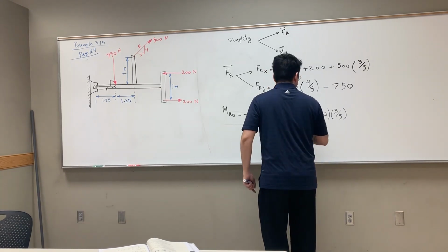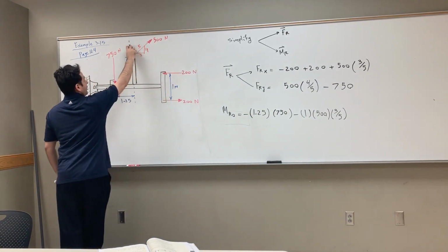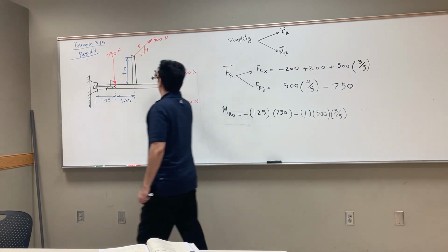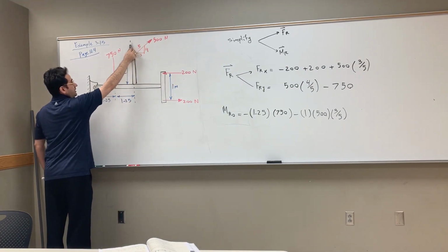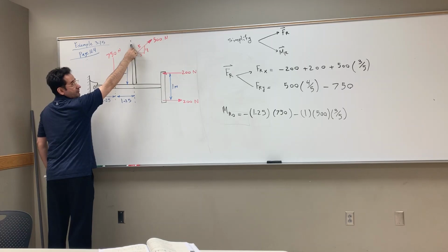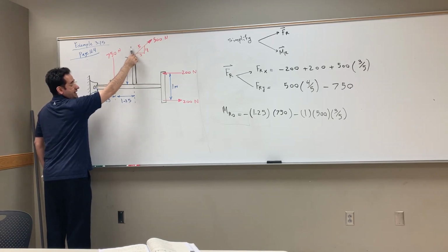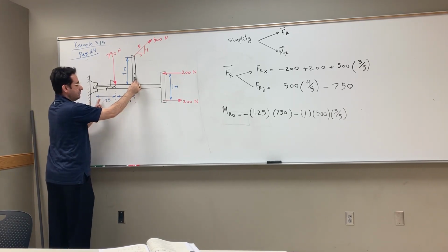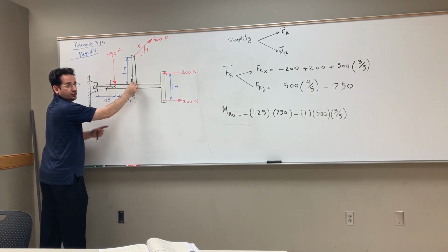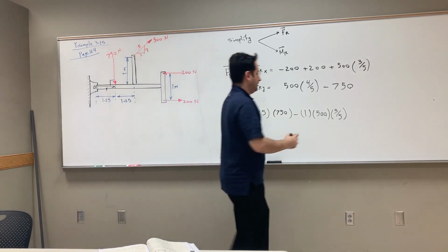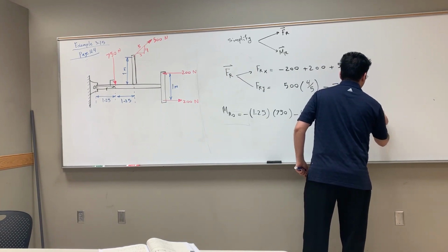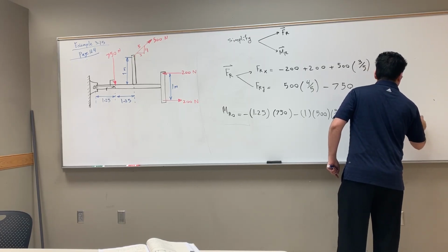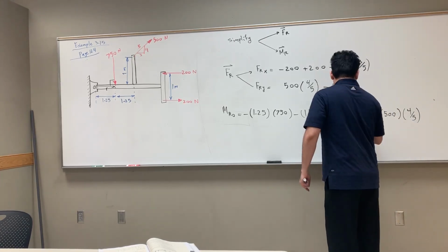Positive or negative? Negative. Thank you, negative. And this one, the Y component, is, let's first explain it actually. So, step 1, break it down. Well, I'll break it Y component. 500, 4 over 5. Now move it. Where should I move it? Down, right here. So what's the moment arm? 2.5. From here to here. 1.25 plus 1.25, 2.5. Right? So moment arm 2.5 times the value of force component, which is 500, 4 over 5. Positive or negative? Positive. Positive, perfect, thank you.